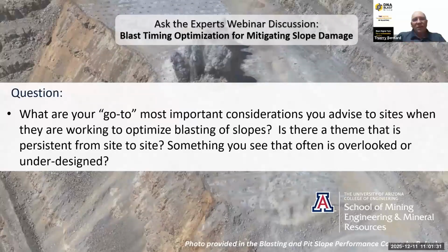From my side, I fully agree with what Chris and Paul said. I will just emphasize that before looking at signature holes and energy distribution, come back to the basics and don't forget your free face. Have a clean free face. Allow the movement of the rock on the other side from the wall. Do not direct the waves directly to the wall. Try to use a sequence that directs the waves to the side or perpendicular to the wall.